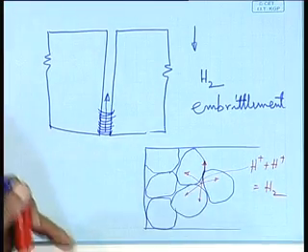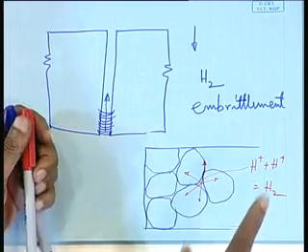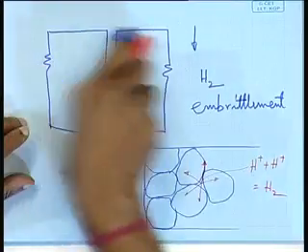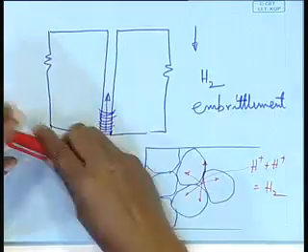That means crack initiation takes place, and then under the action of external forces or thermal stresses, because you have welded, heated and cooled, the crack further propagates and a failure takes place. That means a long crack forms. This phenomenon is referred to as hydrogen embrittlement. So, the culprit is hydrogen.